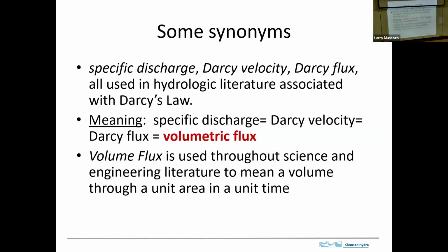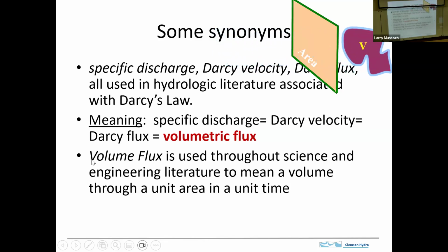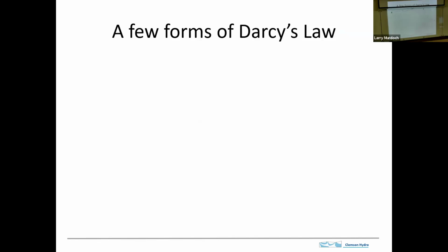But Darcy's law is going to be relating volumetric flux to the head gradient. There's volumetric flux, a volume going through a unit area. Okay, so Darcy's law: if you have the hydraulic head as a function of distance, and you have hydraulic head that looks like that, then the flow is going in that direction.